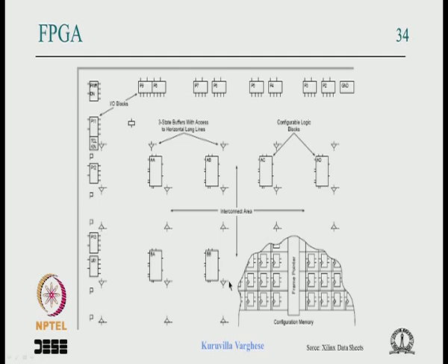So you should know that the FPGA is not just what the designer sees. The designer mainly sees only the logic resources, flip-flops and wires, but there is an underlying configuration overhead logic and circuitry. That makes the FPGA quite big; these wires and switches and the configuration overhead circuitry make the FPGA much bigger, spread out. So you cannot expect the raw speed of an ASIC from an FPGA, but in FPGA you can exploit that it is a programmable fabric, and it is in the control of the designer to put however many computational units within the FPGA.